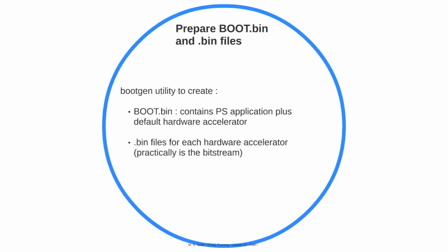So the interesting point about this whole procedure is that whenever you turn on your ZYNQ device, the set of tasks that we do here in our program, they are all being done once by the FSBL himself.